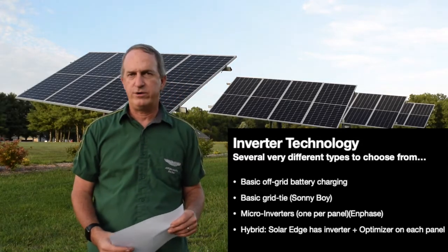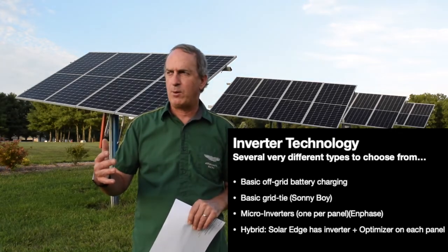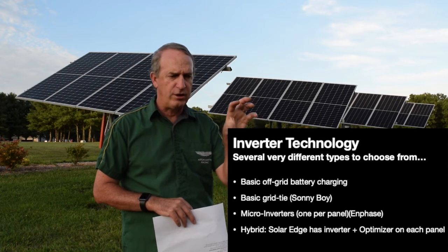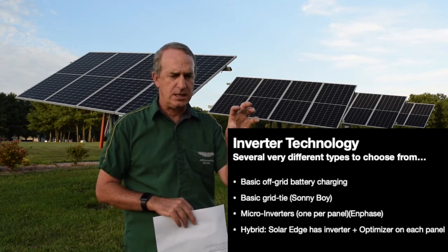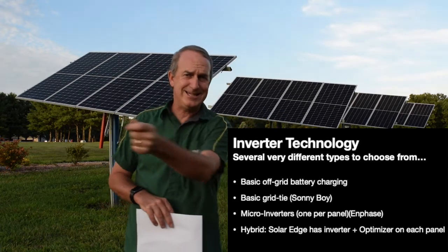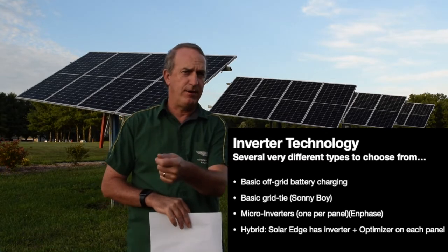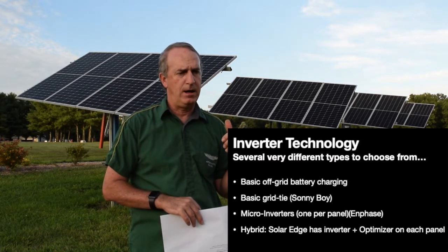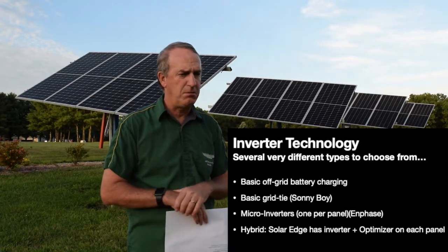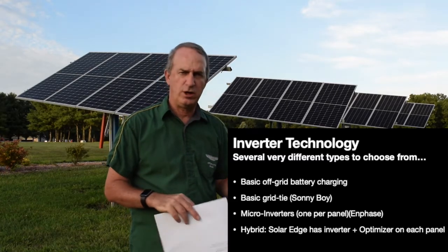Just like what it says in the box. Pretty simple routine. The second kind is where you buy one inverter per solar panel. They're about $100, $150, and they make AC right at the solar panel. Then instead of wiring DC back to the barn, you're running AC right from the panels. AC has the advantage of lower line losses, so your wiring might get a little bit simplified. So that's one way to go.